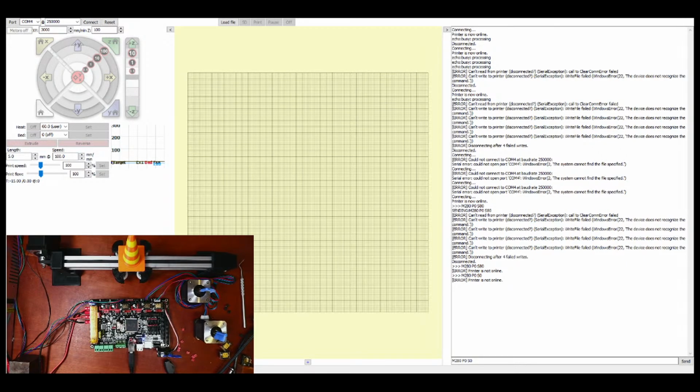So it did move a little. So I'm going to connect again. And I'm going to try and move it 45 degrees. And it moves. So the problem that I was running into, I'll do negative 45 so you can see it go back the other way. That's probably the 0 point, that's why it's hanging like that. But now you know that you can actually do a servo and there are certain requirements to make it run.